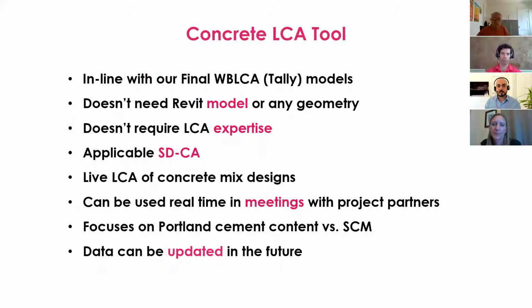This has been in line with our whole building LCA models, which we use Tally for, so the predictions are exactly what we get in Tally. And we've tested this. Eventually we run our whole building LCA, but this is just predicting what we would get for concrete. It doesn't require a Revit model, so it makes it all fast, doesn't require expertise in terms of LCA, and could be done kind of live,